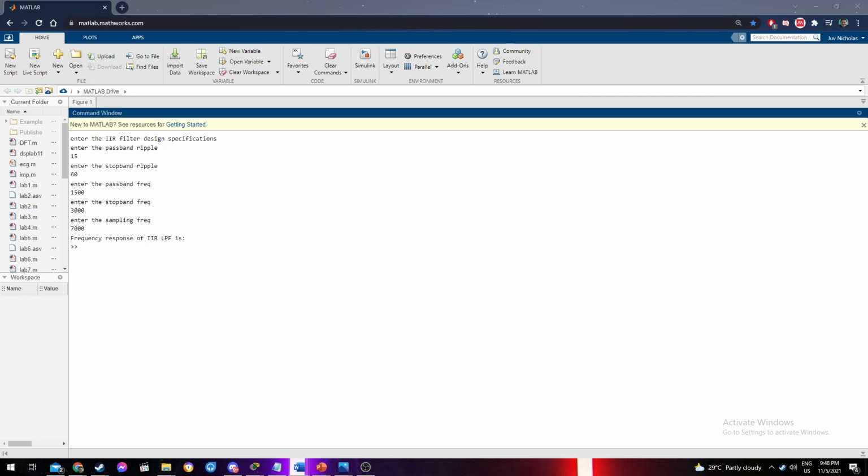solution. There is one problem known as potential instability that is typical of IIR filters only. FIR filters do not have such a problem as they do not have feedback. For this reason, it is always necessary to check after the design process whether the resulting IIR filter is stable